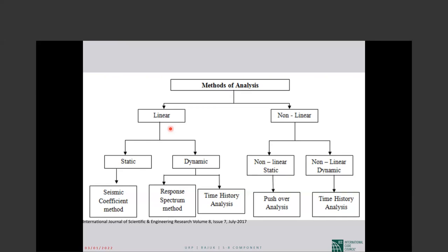So the general approach is not that difficult. When we want to calculate the capacity for the force control actions, there is nothing new in the code for existing buildings. All the formulas for capacity calculation are the same. Just the value of f prime c or fy that we put in the formulas will be lower, the average minus one standard deviation.